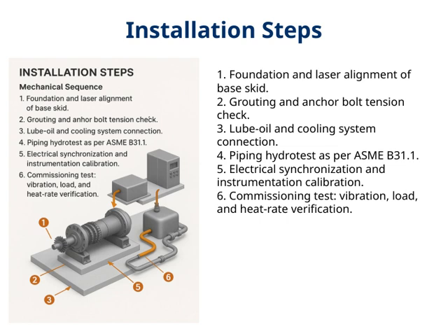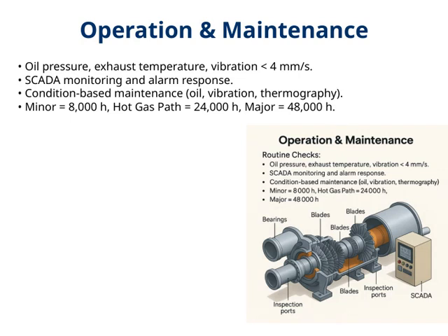Lastly, we carry out a comprehensive commissioning test, including vibration analysis, load testing, and heat rate verification. These tests confirm that the system operates efficiently, safely, and within the designed parameters, tying everything together in the overall success of the installation. Now, let's talk about operation and maintenance.